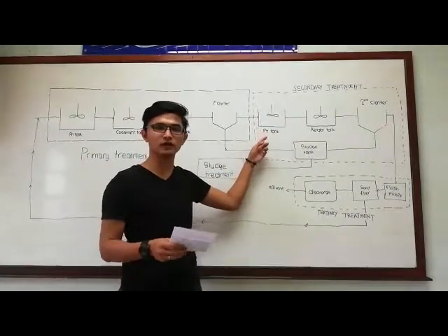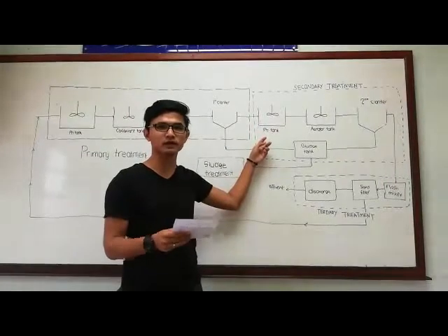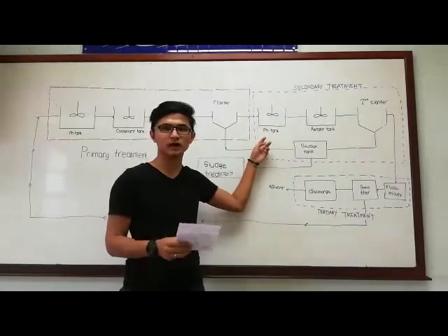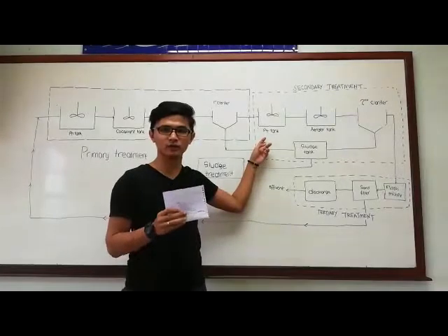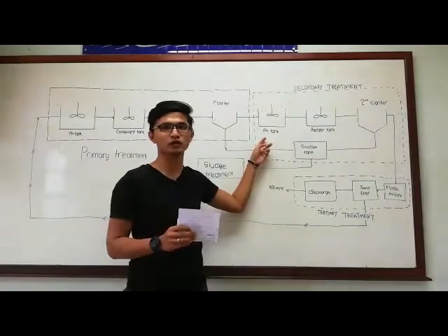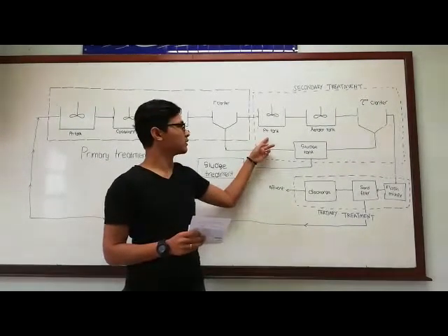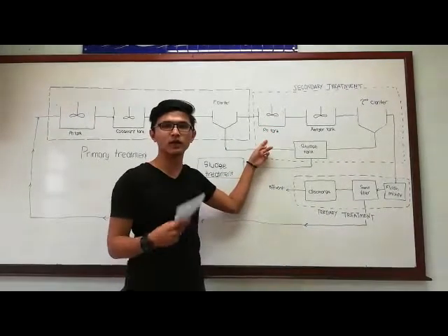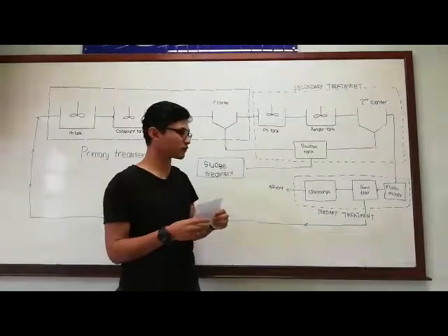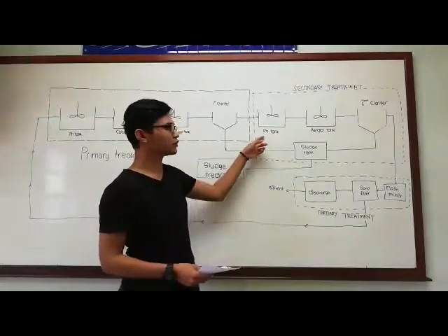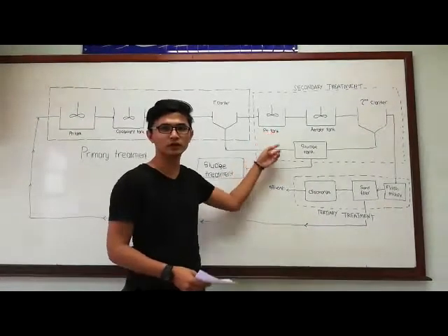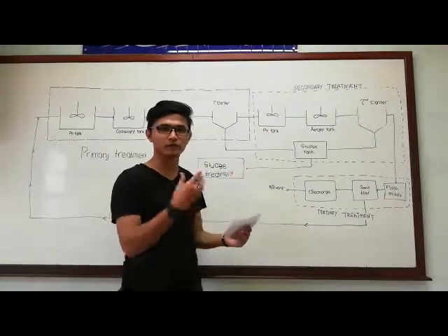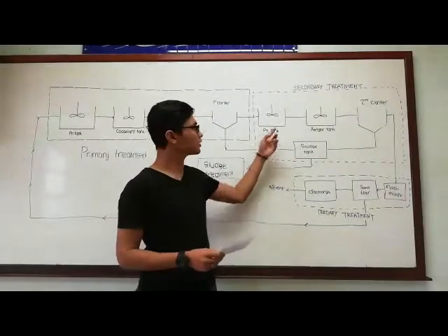For the pH tank, the effluent released by the chemical plant is actually 4.8. But according to the Environmental Quality (Industrial Effluent) Regulations 2009, the pH released by the company is acidic, below the range allowed to be released to the environment. So we have to ensure the pH value is in the range before we can proceed to the next step. So the next step is the aerator tank.